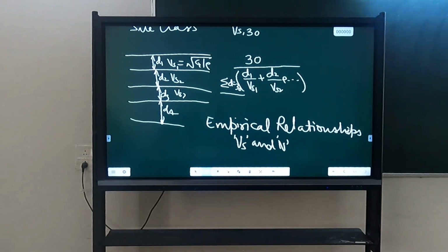The resistance provided by that sand while the wave travels, and the voids in that sand. So on what properties of the sand are you defining the shear wave velocity? Properties of sand may be density, c, phi, angle of friction. It will depend on density, that is, how much compaction has taken place, which is represented by the density and the phi value. Basically it will depend on these parameters.